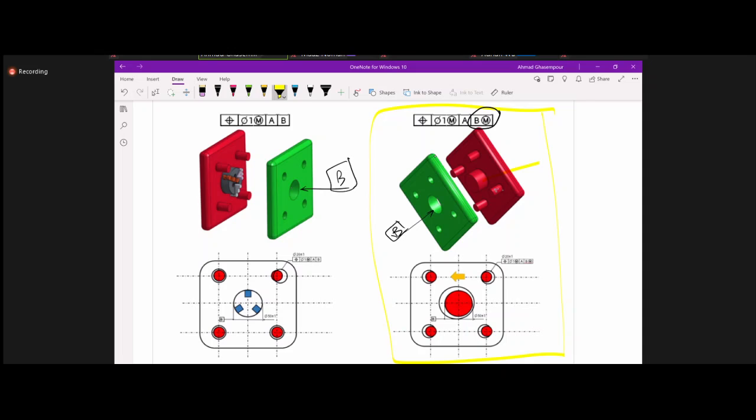Whereas if that M doesn't exist, which is the situation here, there has to be contact between datum B and the part that attaches to it. So when would you have contact in that central feature? It's either something like a chuck that you can see in the picture, like a 3-jaw chuck, or if it's a press fit.